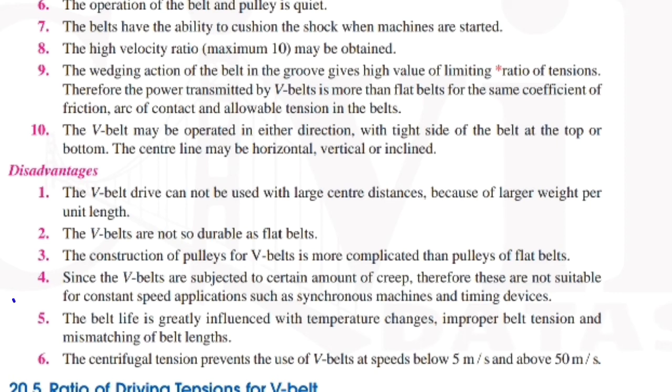And the fifth disadvantage of V belts is that the belt life is greatly affected by temperature changes, improper belt tension and mismatching of belt lengths. So these are the disadvantages of V belts.